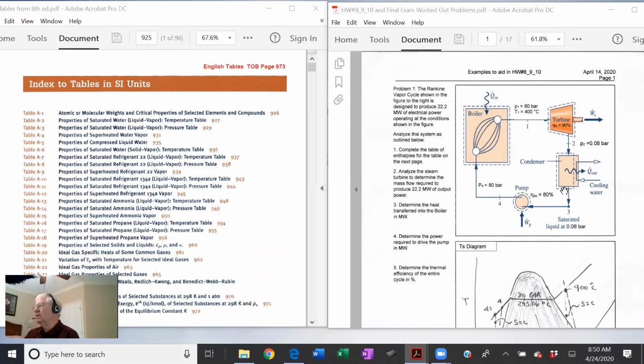If you look at this schematic here, you see this is a Rankine power cycle. It has the four elements of the power cycle. It has the turbine, which produces the work to drive the generator. It has the condenser, which takes the low pressure, hot, mostly vapor out of the turbine after it's exhausted a lot of its energy, and condenses it, turns it into liquid water.